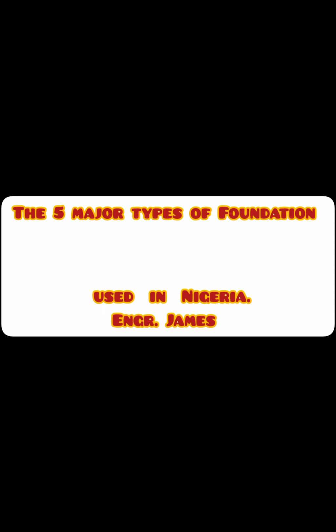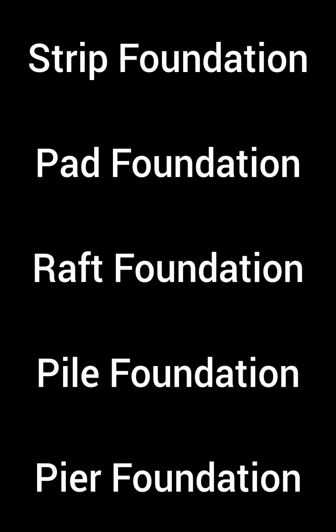Majorly used in Nigeria. And I would like you to note that these foundations are chosen based on certain criteria. So one of the criteria is the load requirement, the type of structure that is being built, and soil conditions. So these are the requirements that necessitate the type of foundation you use on your land.